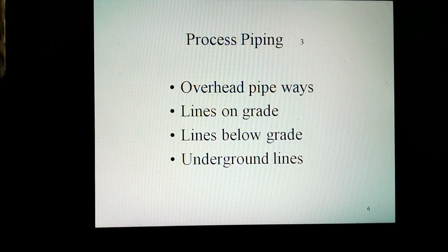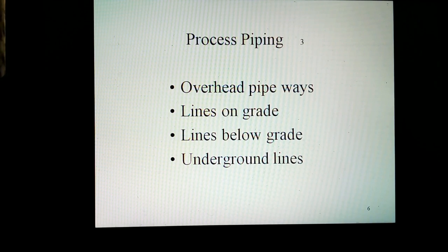Process piping. Locate all pipe lines in major process units on overhead pipeways. In certain instances, pipes may be buried, providing they are adequately protected. Lines that must be run below grade and must be periodically inspected or replaced should be identified on the P&ID and placed in covered concrete trenches. Cooling water lines normally may be run above or below ground, based on economics. Domestic or potable water and fire water lines should be run underground.